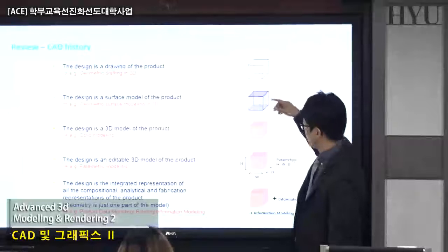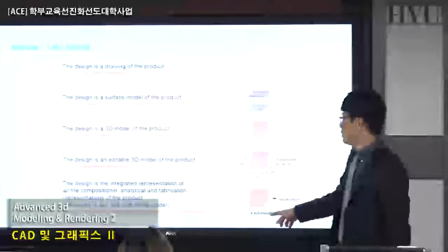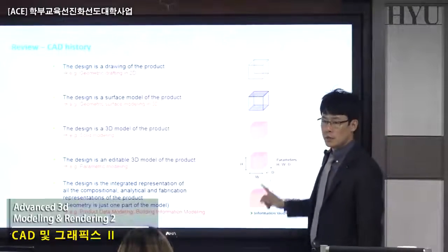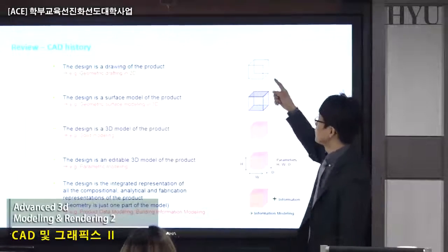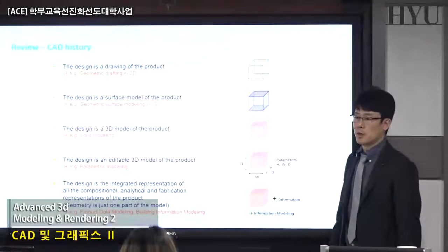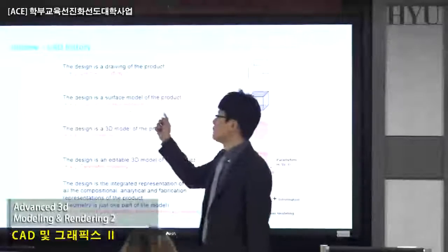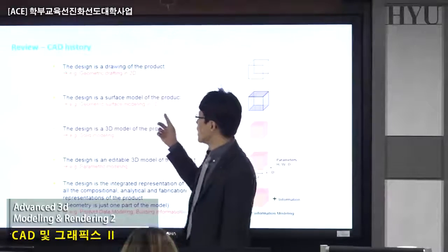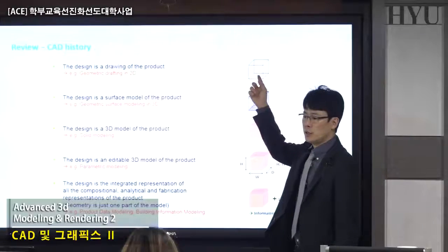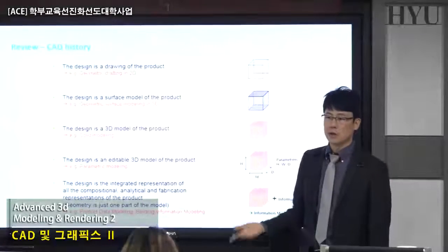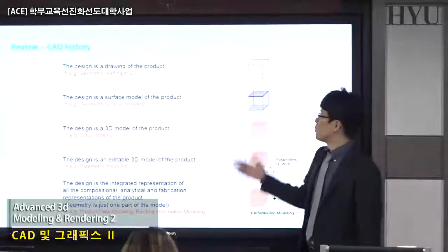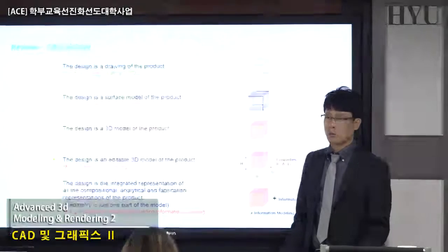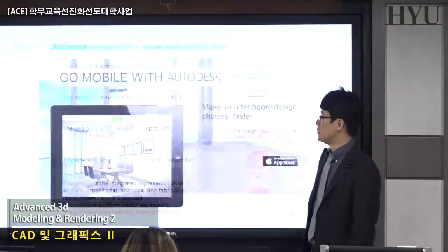This is the history diagram that I show you. I told you this is the largest one. This one contains this one, also contains in this direction, okay? This one is subset of this 3D surface-based model. That is why if you design your object by SketchUp or 3D Max, you can easily generate 2D section, 2D elevation, floor plans by using some orthogonal view, not perspective view, okay? They are all standardized views.